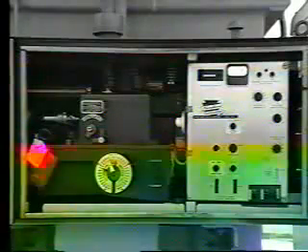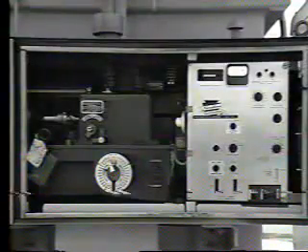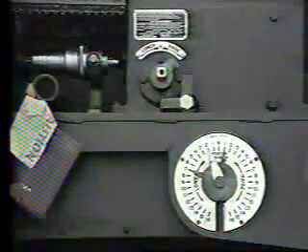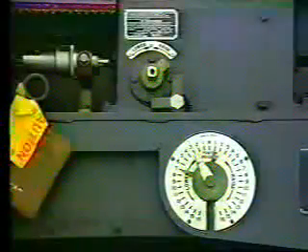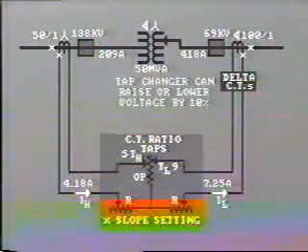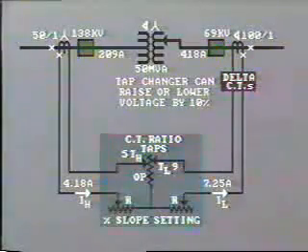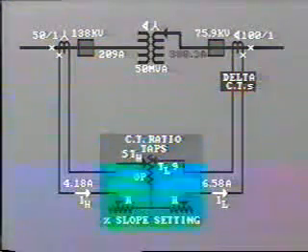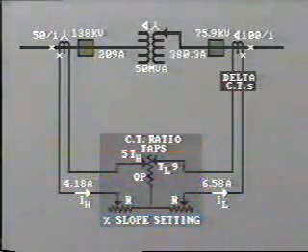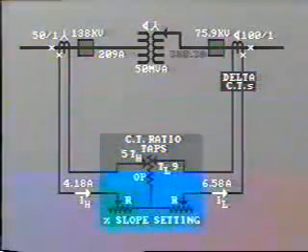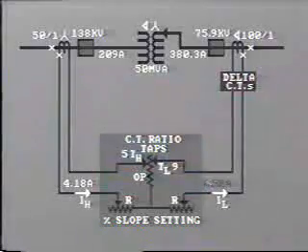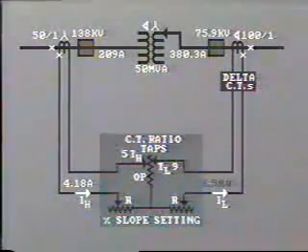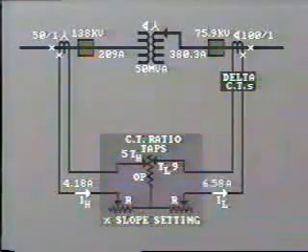When the transformer has load tap changing, the voltage ratio across the transformer can change, and with it, the percentage mismatch. The CT ratio selection should be made with the tap changer in the mid position. Suppose in our previous example, the tap changer could raise or lower the secondary voltage by 10%. On the upper tap, that would be 75.9 kV. The line current in the secondary would now be 50,000 divided by root 3 times 75.9, which equals 380.3 amps. The secondary current in the restraint winding would now be 380.3 divided by 100 times root 3, or 6.58 amps.